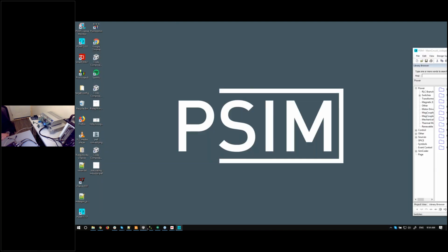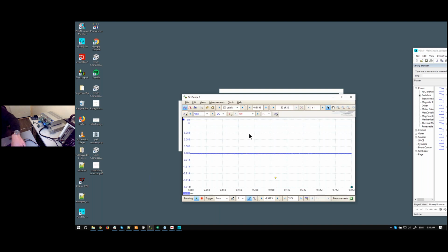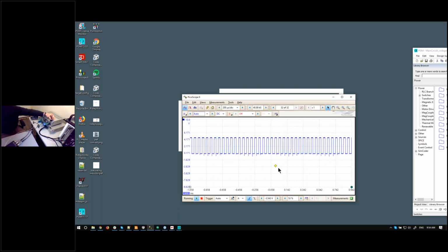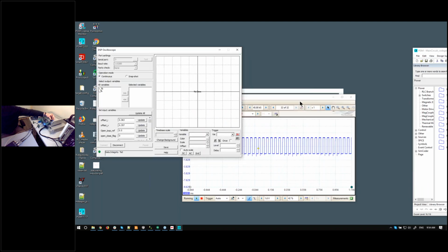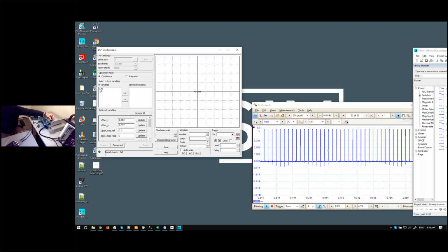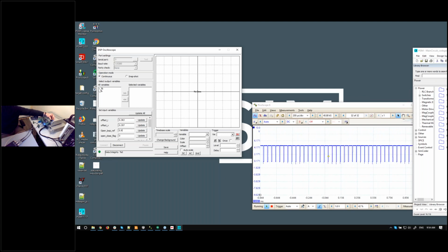So what we can look at is we should see PWMs right now. This is a little oscilloscope you're looking at, and we should see 50% duty cycle. And then I can also, on the fly, change that, say, let's go to 10%. So there's 10%, and there's 90%. So I'm able to control this. This whole thing is working in real time.